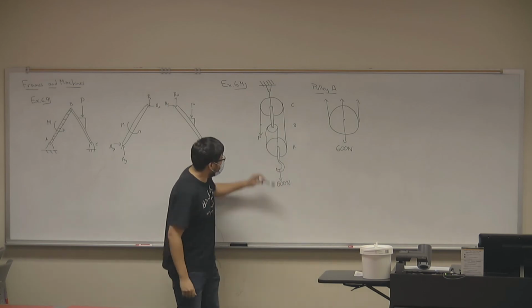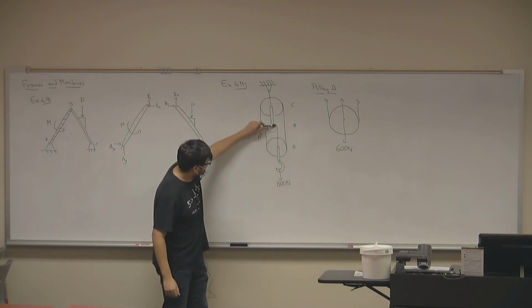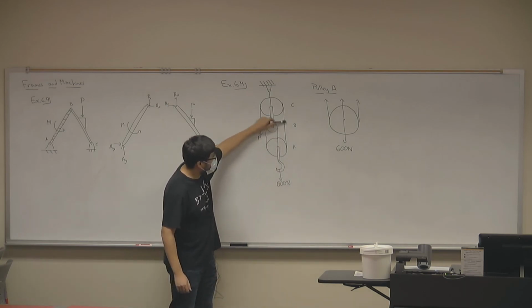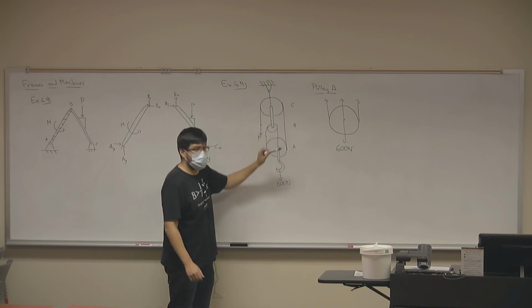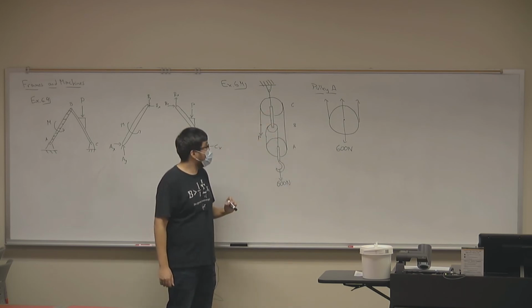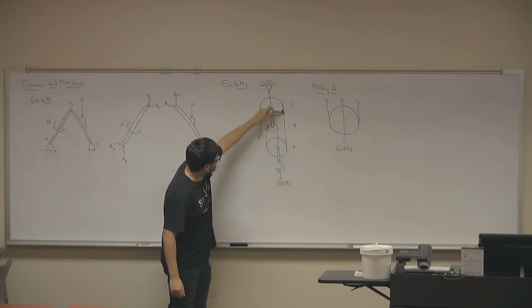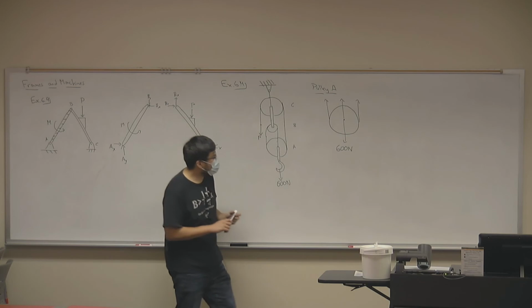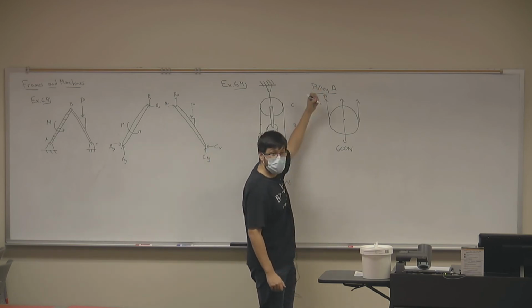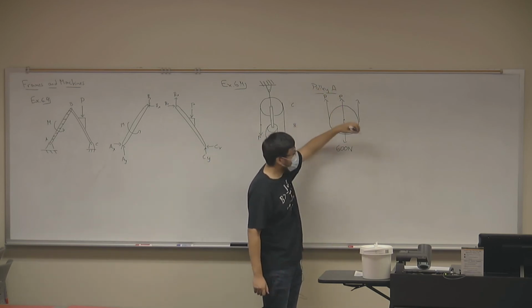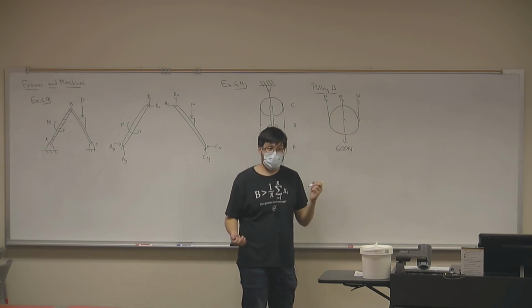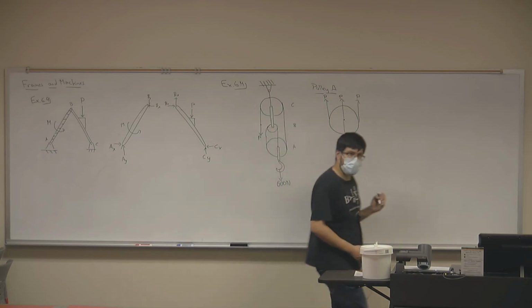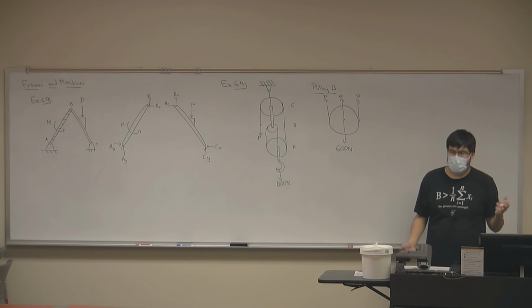Exactly, right? So the force along this cable has to be the same throughout the entire cable. And notice, what is that force? If we go all the way through the cable, what is that force equal to? P, right? So what we have is a force of P, P, P. So now can we solve this system using equations of statics?